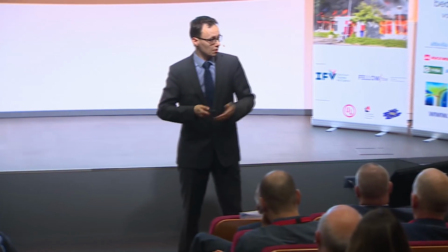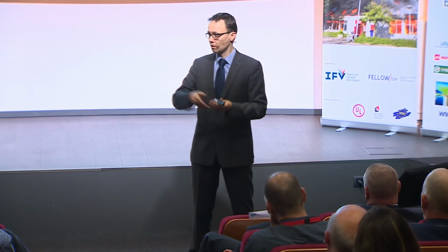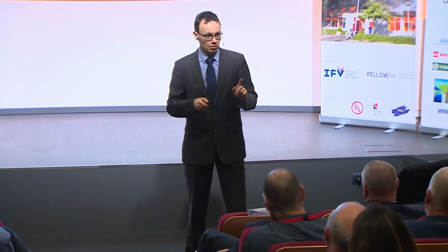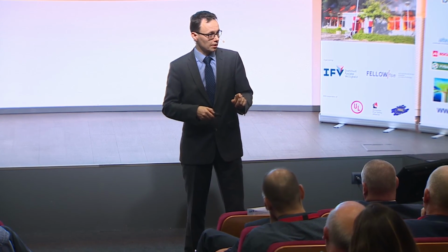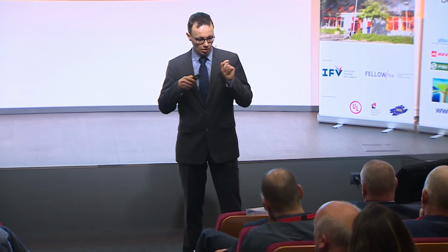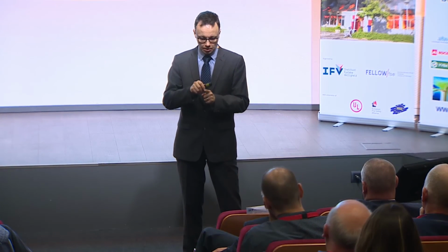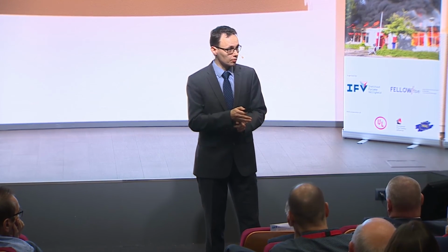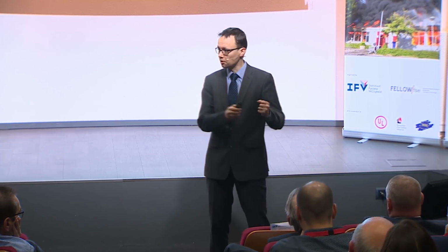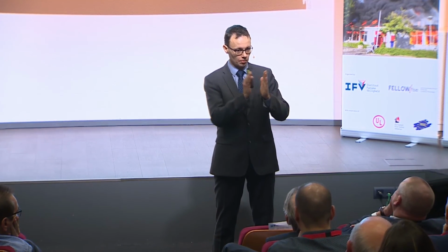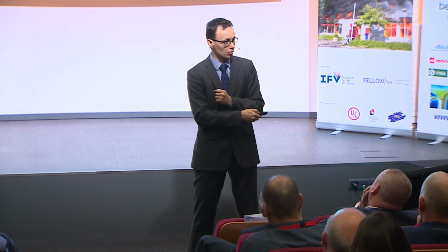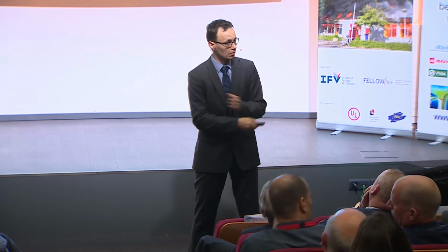This fall we made another project. We had a sprinklered healthcare center in Finland. We did a similar study in patient rooms. We did 30 fires in sprinklered patient rooms, and in almost all the tests, the sprinklers went off in about 1 minute. Up to this point, it was really difficult to keep the door closed to the corridor. The firemen really had to lean on the door if they wanted to keep it closed, because of the overpressure.